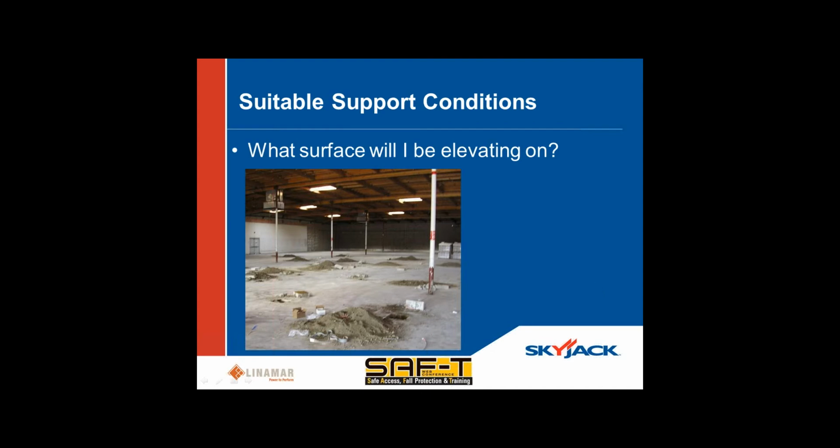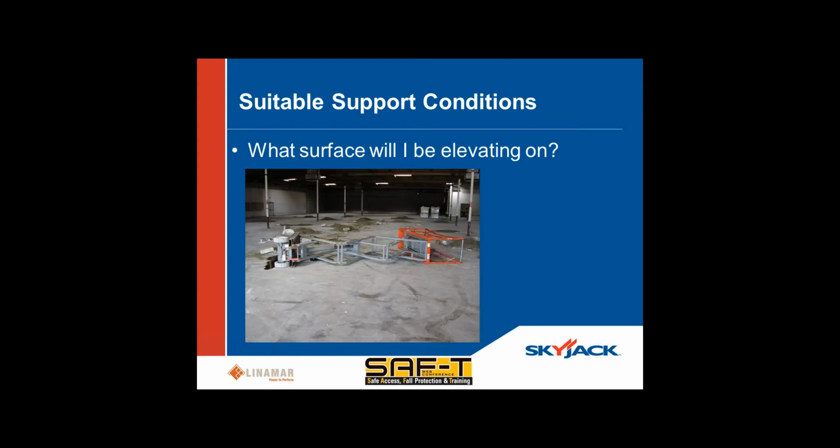So if I look at some surfaces, this is maybe a little bit extreme, but certainly a surface like this, you really have to understand that in a lot of cases your slab lift, aerial lift, scissor lift, or whatever type of lift it is, a lot of them are not really suitable for this kind of environment. You will have to take some precautions to ensure that you don't have people driving into or around various holes on site. And unfortunately, when you don't do this, that is what can potentially happen, and obviously has happened, in the past.